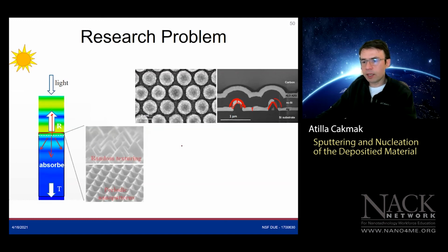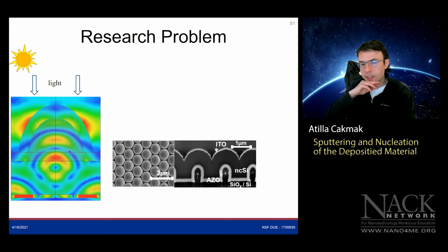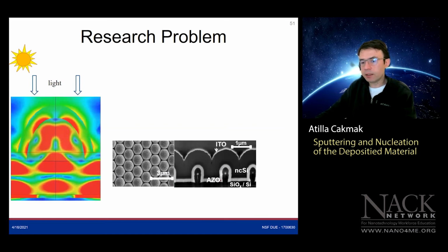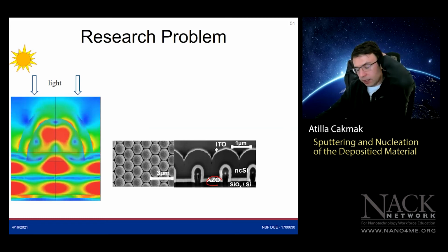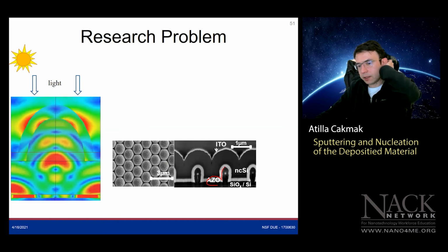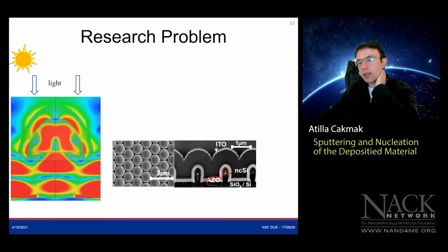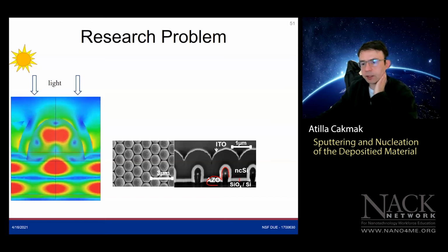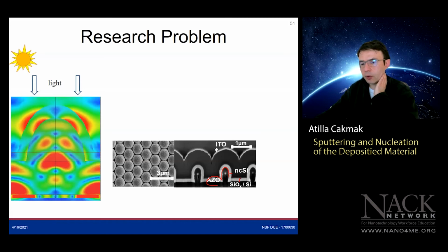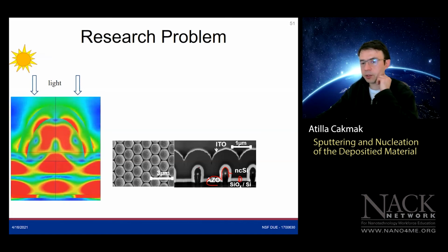But I will show you next week, actually the week after next, with the atomic layer deposition that we switched to back in the day, with aluminum zinc oxide, now not coated with silver, on these little dome structures. We switched to atomic layer deposition, and in that case you see we've got a really conformal coating, meaning the height on the sidewalls and the planar surfaces are equal to each other.